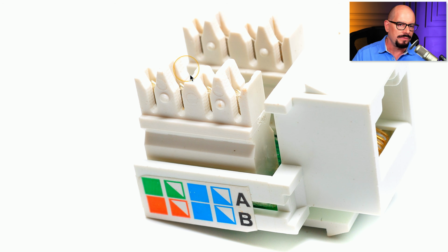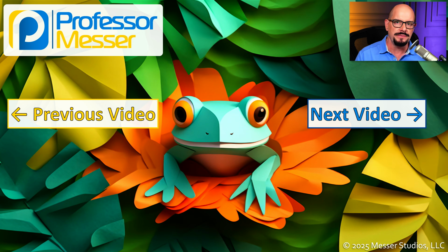Here's another example with a different keystone jack. You can see that there are 4 wires that go on this side of the jack and 4 wires on the other side of the jack. This jack shows us if you're using T568A, you would put a green, a white and green, a blue, and a white and blue into those 4 areas, and you would punch them down. If you're using 568B, you would use orange, white and orange, and blue and white and blue. And on the other side of the jack are the other 4 wires, and you would put them in with the same color scheme that's specified for either T568A or T568B.